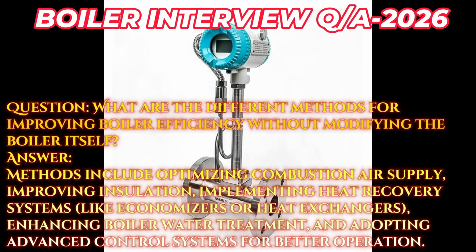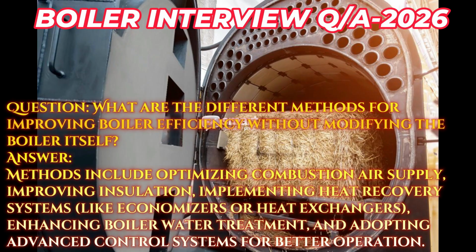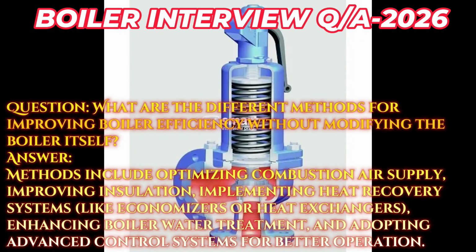Question. What are the different methods for improving boiler efficiency without modifying the boiler itself? Answer. Methods include optimizing combustion air supply, improving insulation, implementing heat recovery systems like economizers or heat exchangers, enhancing boiler water treatment, and adopting advanced control systems for better operation.